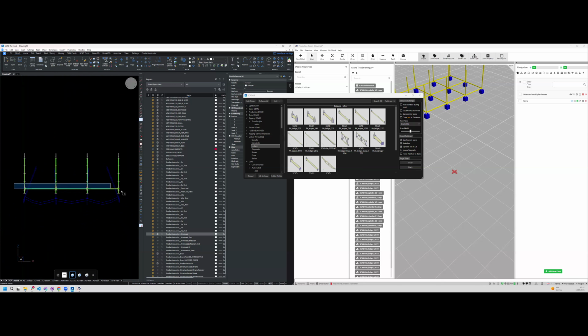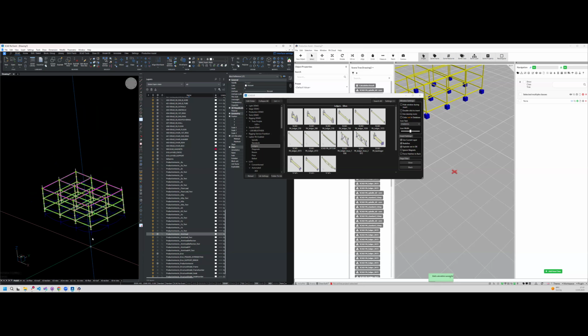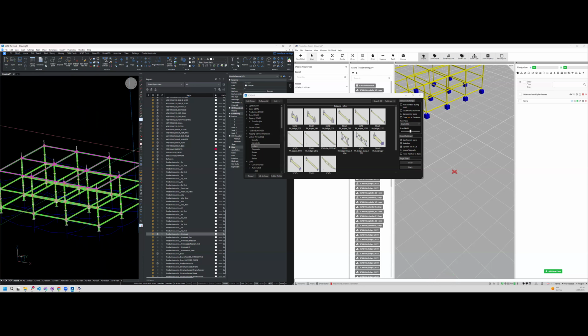So what I'm doing is I'm selecting this, and now the next menu command is CZ, so copy in Z direction. When you're building a stage, normally the first layers need to be compact. So when I move this up, I only want to do this by 1000. Then enter and enter, and then I have the first two layers with the 1000 pieces in here. You see it's also automatically calculated and done like this, so that you can see it and actually can change it.